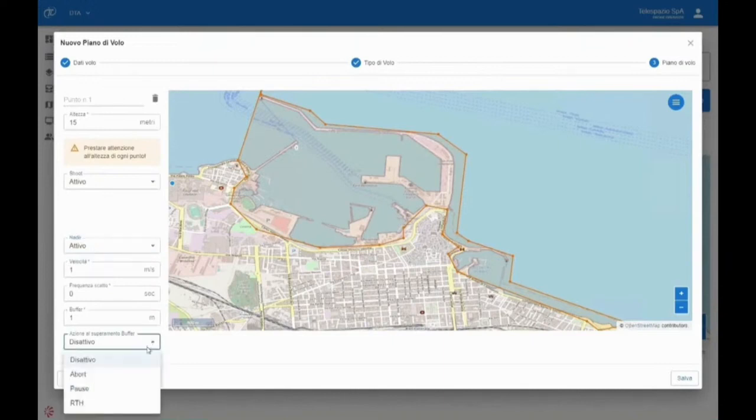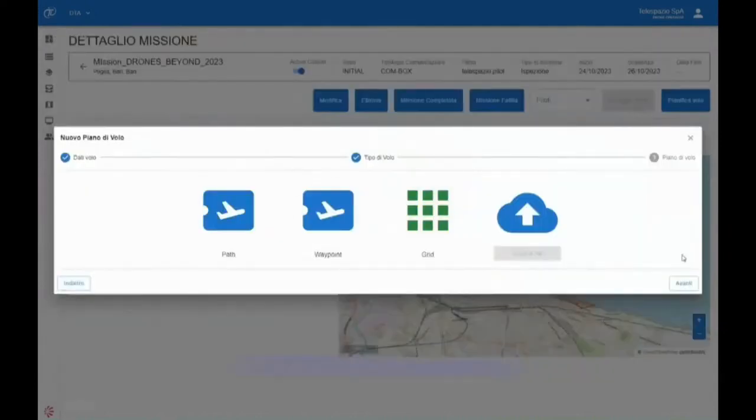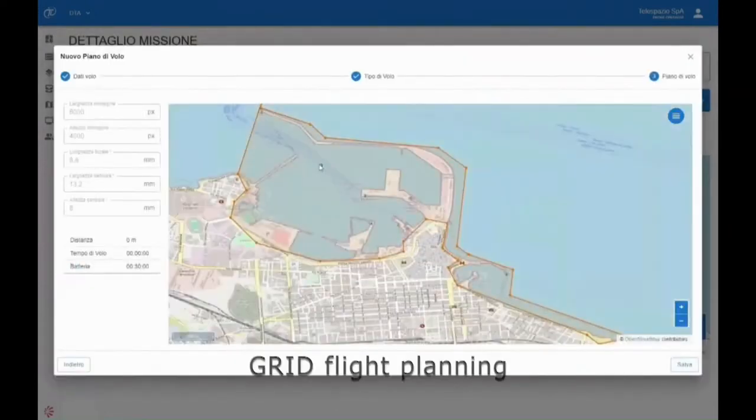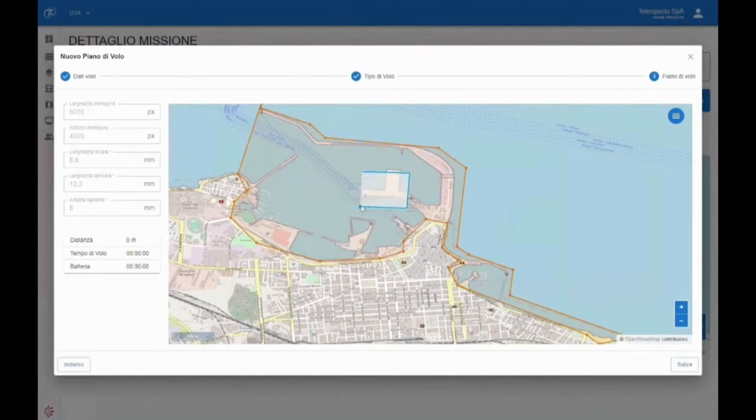At a certain point, of course, you have to do flight planning. Of course, people use DJI tools or Mission Planner if they use Mavlink drones, or other tools. We provide default planning tools, as in this case for manual planning, or, as we can see in the next figure, grid planning for automatic planning, designing the boundaries of a mission and providing you an automatic flight plan that you can change. An example is modifying parameters such as the GSD that can influence the height.